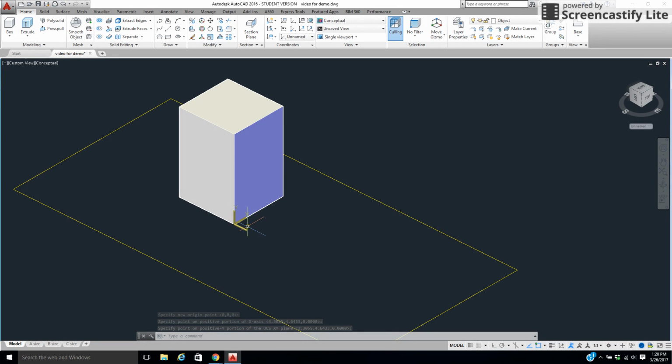That's all fine and well, but I want to slice it going back. So what I'm going to do with this is I'm coming up here now, and I'm going to rotate on my X. And notice I pull it forward, go back. Let's just take this and let's go back a negative 45 degrees. So see how this UCS is sitting there at that angle? Now remember, that's a one-step process. Don't forget, if I needed to save this slanted UCS, I could always go in and type in my UCS and hit S for save, and that UCS I can name, but I'm not going to worry about that. So I've got that just sitting right there now.